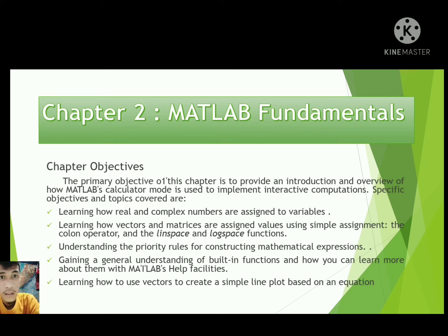Number 1, learning how real and complex numbers are assigned to variables. 2, learning how vectors and matrices are assigned values using simple assignment, the colon operator, and the linspace and logspace functions. 3, understanding the priority rules for constructing mathematical expressions. 4, gaining a general understanding of built-in functions and how you can learn more about them with MATLAB help facilities. 5, learning how to use vectors to create a simple line plot based on an equation.